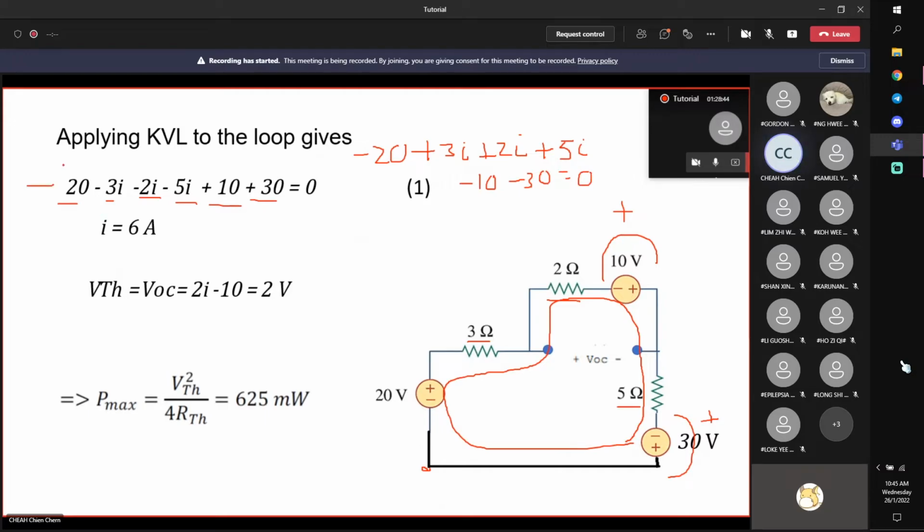Now you look at this equation, it's just to multiply this by negative, right? You get exactly the same thing. That's why I say that it's a matter of your own preference. Fix one which you think you can write down with accuracy, precisely, right? Okay, one unknown only. That means that I assign this mesh current I. It's this current I, right? And it's flowing through all places because this is open. And I solve for I, 6 ampere. But that's not what I want. I want VOC, right? Now, how do I get VOC?